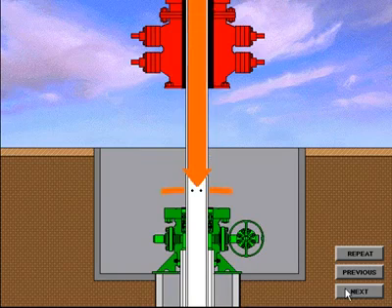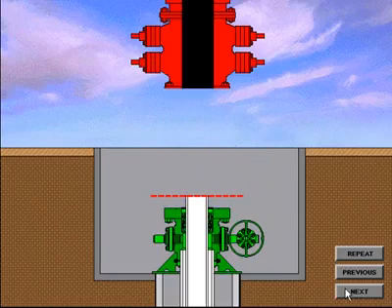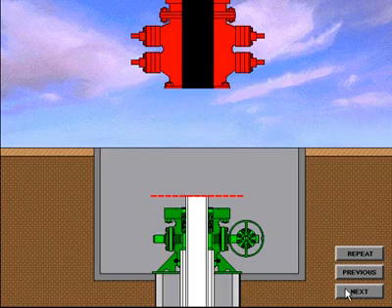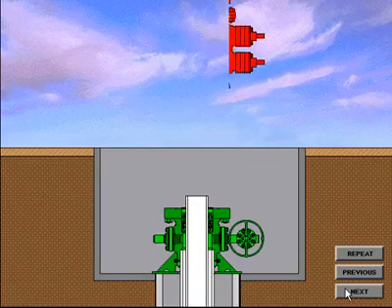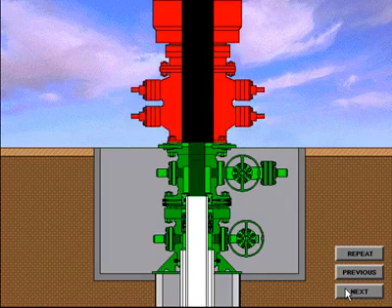Holes are cut in the casing to allow the drilling fluids to drain out of the casing riser. When the casing is drained, a rough cut is made and the balance of the casing riser is removed. The BOP system is removed. The casing spool with a crossover seal is installed. The BOP system is nippled up and preparation is made to drill out for the production casing string.